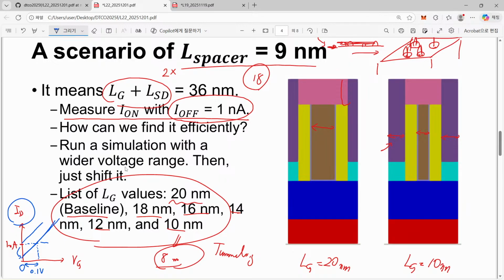Can we change the gate work function by 0.1 eV quite properly? We assume that device engineers have some capability to shift their curves by adjusting their work function and metal stack. That is our assumption.